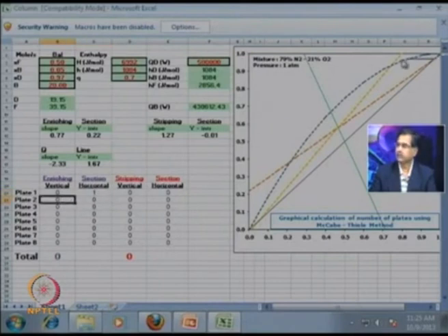So, this is what I get, the corresponding liquid for the topmost plate, where I draw a horizontal line, and on the equilibrium curve I get the corresponding liquid point. Now, I will come down. So, the staircasing method starts: I come vertically down, which I come here, and this is where I come on the operating line for the enriching section. I get this point, now I go horizontally again as I have explained earlier.